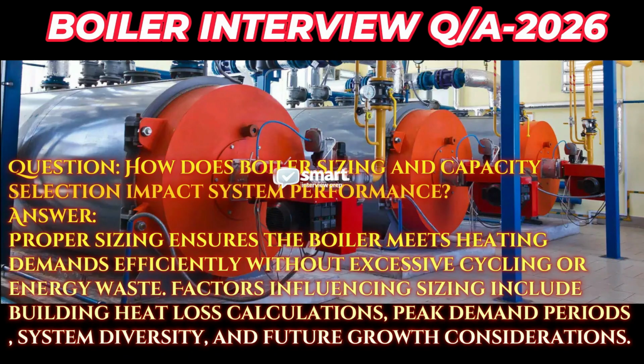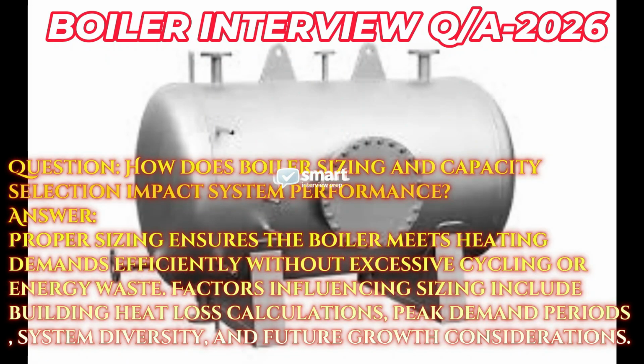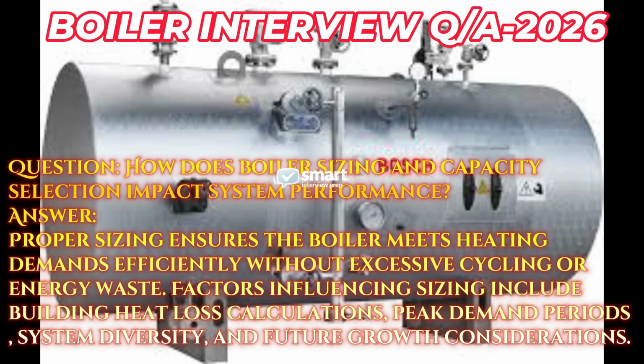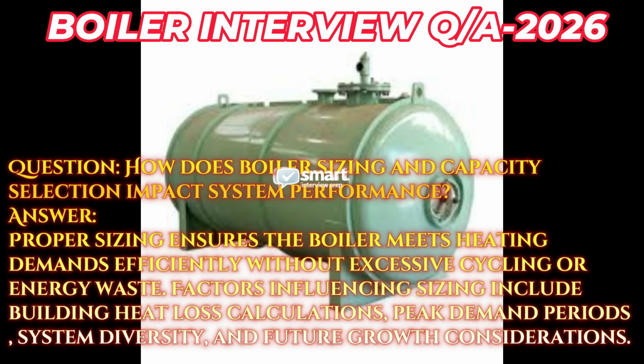Question: how does boiler sizing and capacity selection impact system performance? Answer: proper sizing ensures the boiler meets heating demands efficiently without excessive cycling or energy waste. Factors influencing sizing include building heat loss calculations, peak demand periods, system diversity, and future growth considerations.